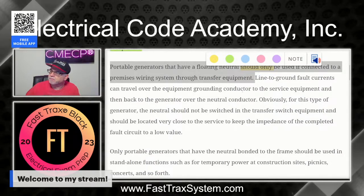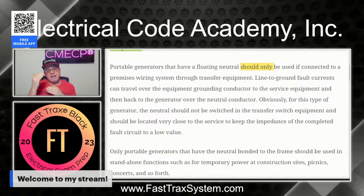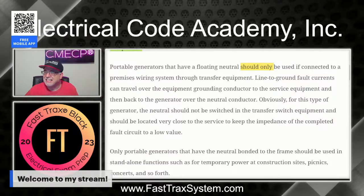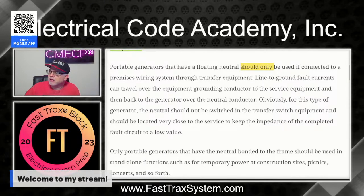Okay, now, because if it is floating neutral, by the way, then you've got the separation, right, you don't have any jumper between the neutral and the frame. Okay, that type of scenario. So it's technically not a separately derived system at that point. Okay. All right, so let's look at what we're dealing with here.